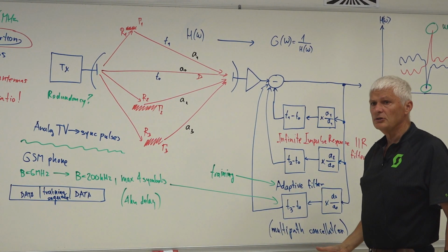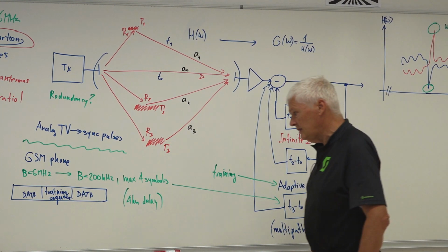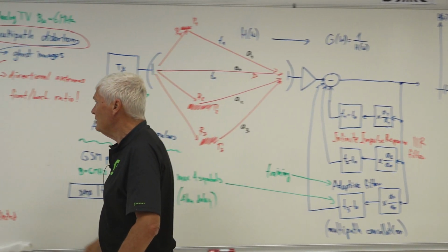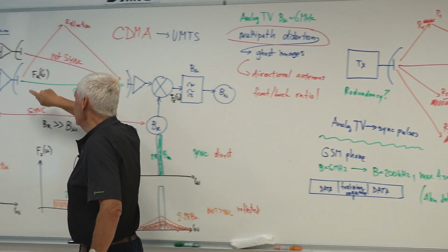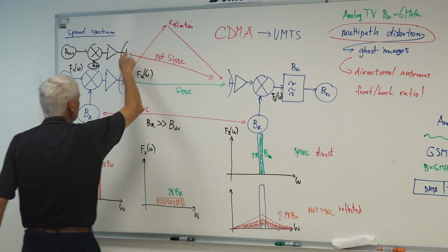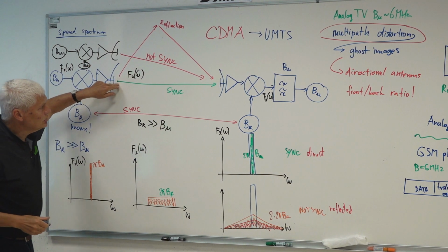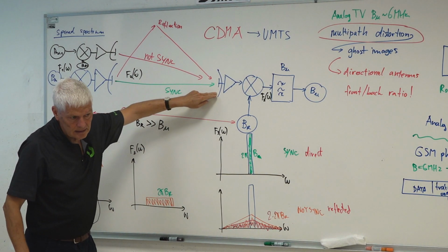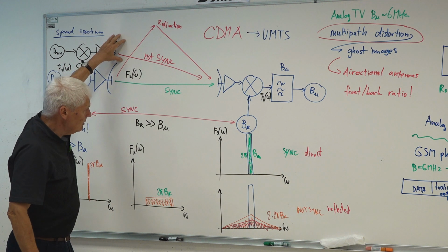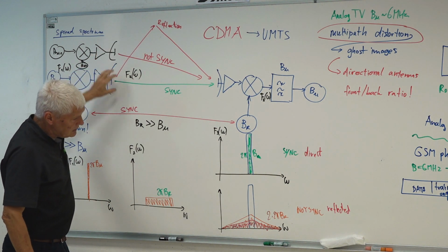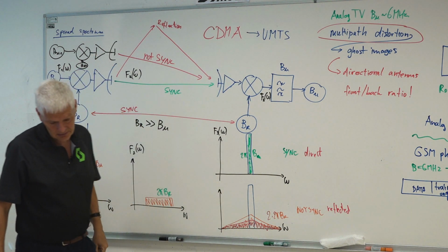It was also very difficult. CDMA was also very difficult to handle, because if I had code division multiple access, then I should carefully monitor the powers of the transmitters. All transmitters should come at the same power at the receiver, because if the interferer was much stronger than the useful transmitter, then we gained nothing here.